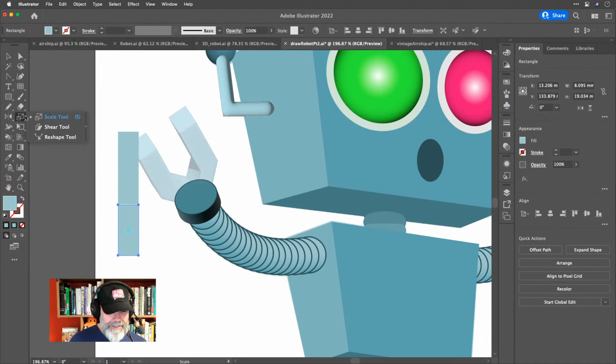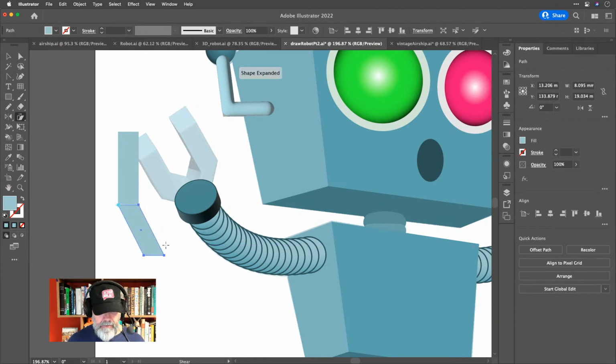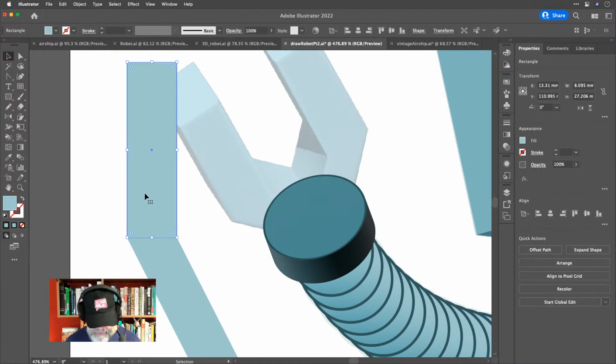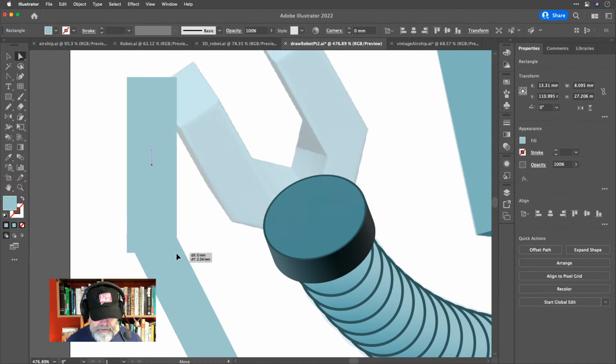So I'm going to choose the shear tool, and I am going to click on that top left hand point just there, okay, to set the transformation point. I'm then going to drag across like so, and if I hold down shift, okay, it keeps that regular like that. There we are. Good. So I've got those two things. I don't think they did quite connect, you know. There we are. They are now. Something like that.